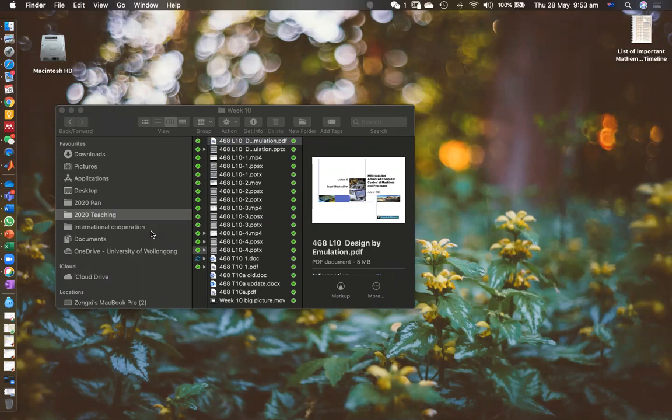So from that, for the first order system, the phase goes from 0 to negative 90 degrees if you have one pole. For the second order system, each pole will move that 90 degrees, so the second order system goes from 0 to negative 180. Okay, so that's how the system works.